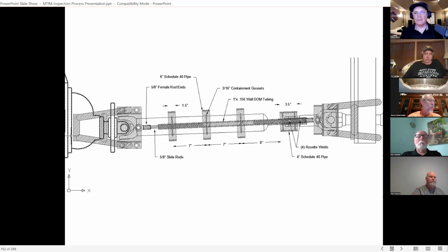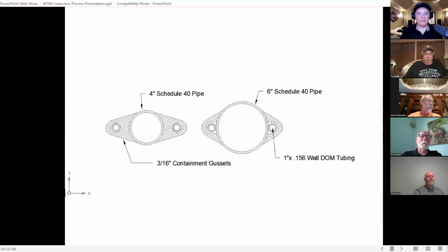This is the deal, and it's not up for discussion. You get these, they don't crack. They don't require all kinds of maintenance. They require at least one end to rotate. We've got these different pins on the ends that hold the heim joints. All this is clearly specified in the rules. They're very, very specific about what we allow.